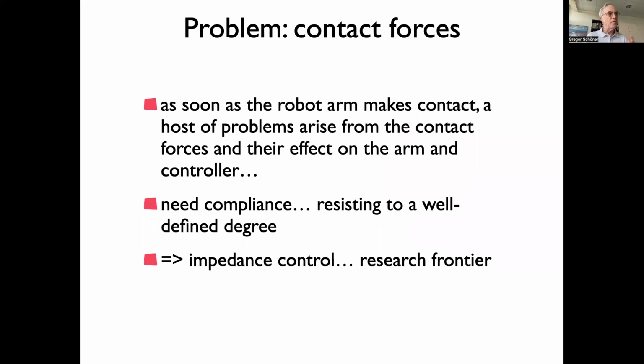The major problem, where there's a lot of research in conventional robotics, is to deal with contact forces. Currently, when robots actually have mechanical interaction with something, only very crude things are done. A lot of the robots just paint, where there's pretty much no physical interaction, or do some spraying, or point welding, where you just have to hold the arm in a certain position, at a certain distance, but no physical contact, right?